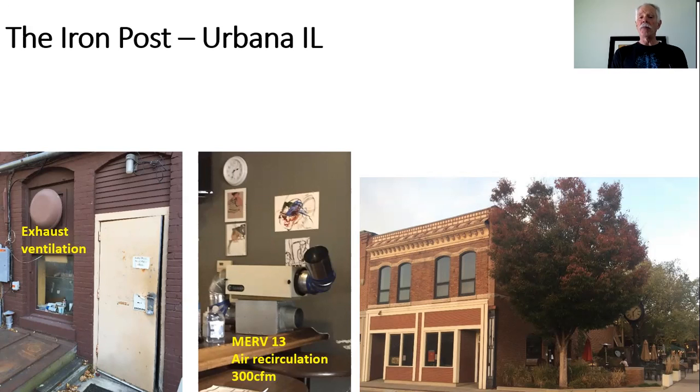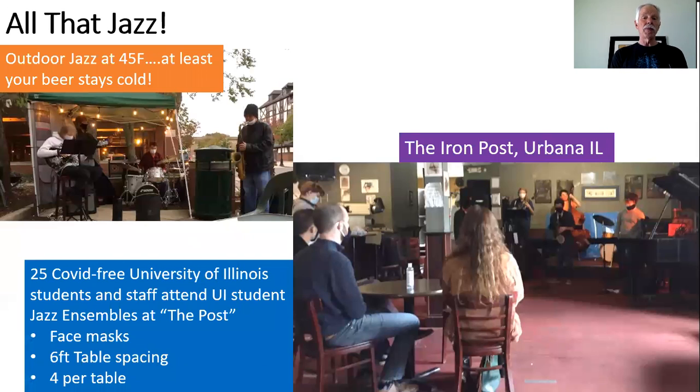With the measurement instruments, we could measure particulates down as small as 0.3 microns in diameter, over the expected range of what we sneeze and cough and what we respirate through our breathing. We could measure the size of the particulates and their density in this air as we changed the fresh air ventilation level and the filtration level. So it's a realistic venue and real measurements, to see that what we recommend works in the field.